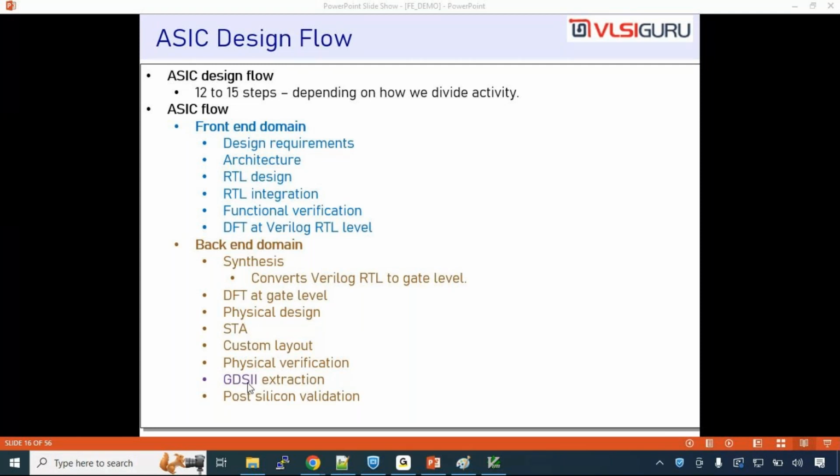So you understood what GDS2 is? Very simple. If silicon is there, where is the metal? Where is the oxide? Where is the polysilicon? Where is the doping? How much doping? Like that, millions of such descriptions they will give. The foundry, the TSMC company, will understand all that. They will do the whole process in that manner. So to understand that, you need to understand the IC fabrication flow. I mean, what will they do? First, they will do the etching, then they will deposit the metal, they will do the doping, they will do etching, then they will deposit oxide, then on that they will deposit polysilicon. They do something similar in a very complex manner. So that description is called GDS2.